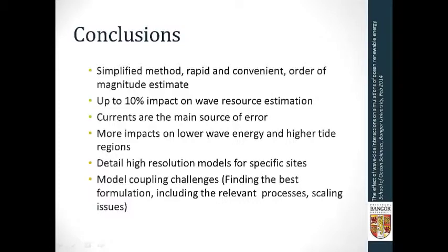The conclusion here is that the tide or current flows can significantly alter the wave climate. I think that's what people who study wave-current interaction expect. In terms of the actual method of approach here, presumably you maintain other calibrated parameters in the SWAN model the same in both runs. There's no attempt to look at the variability of the other calibration parameters. You just fix those and then look at the impact.